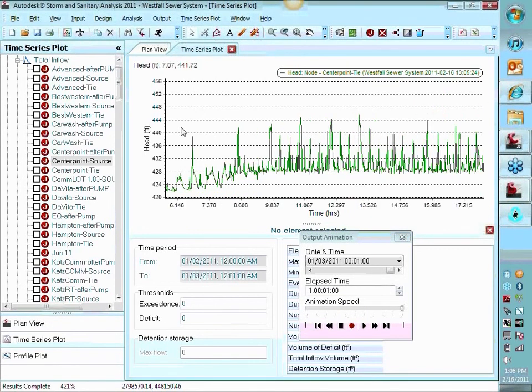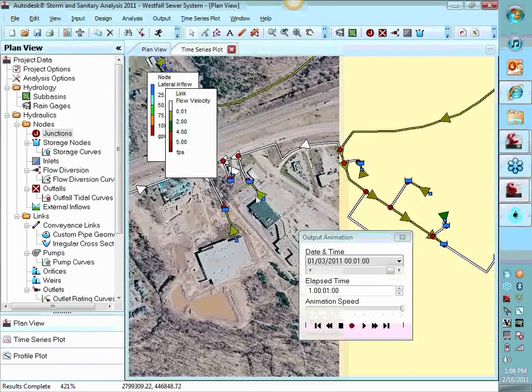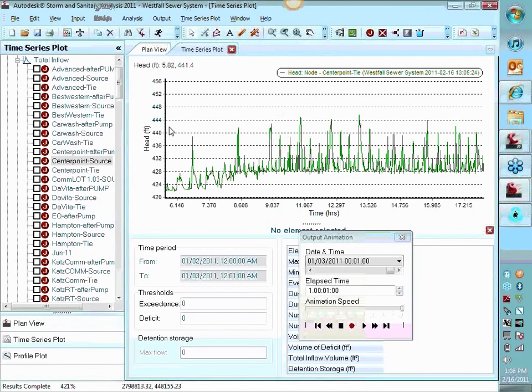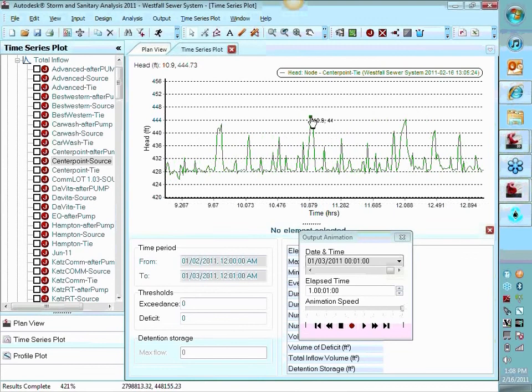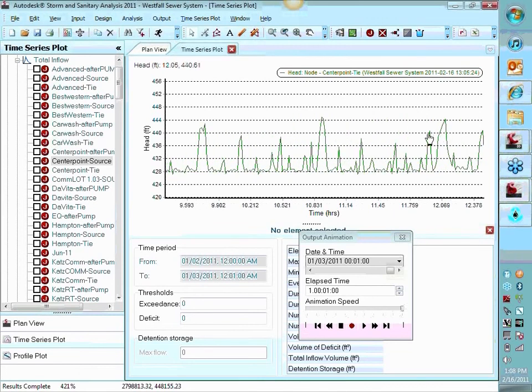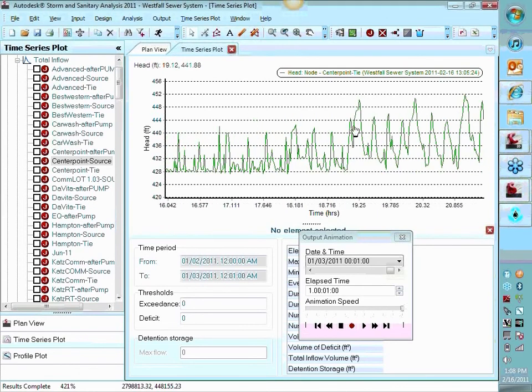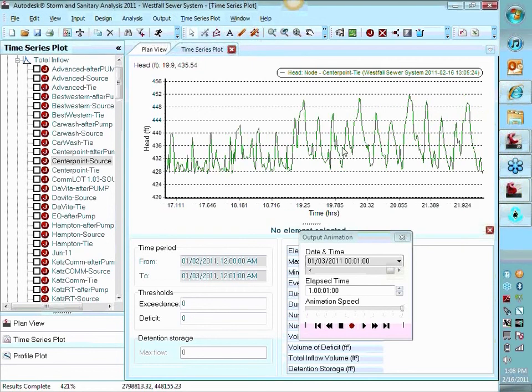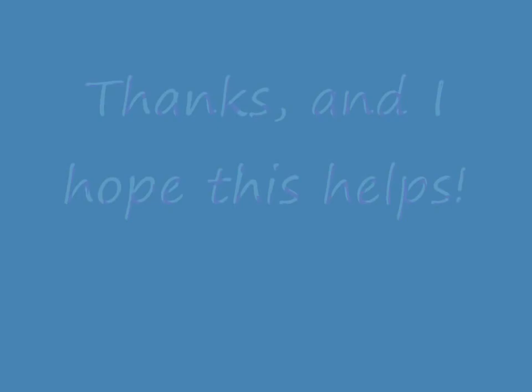And some of the things we're trying to pull away from here is the shutoff head for the pump for this station right here. That is the head elevation where it can't pump past it. It will basically turn on but no flow goes out because there's too much pressure to push against. It is 146. So we are right at it for that, and it's a private pump station, and here we're above it. So at this time in the system, when that development's pump station turns on, no water comes out, and that wears on the impellers on the pump, and the pumps will start to wear out.